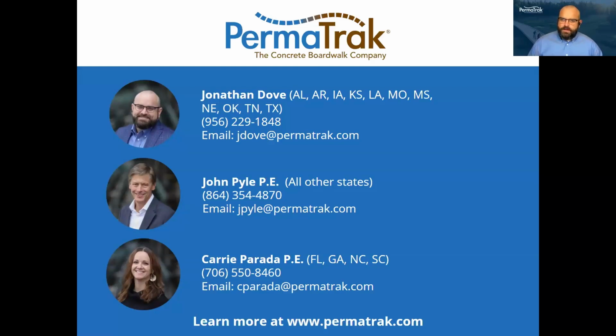That was great. So we had a specific project question where the water was diverted under a boardwalk and washed out some of the foundations, exposing a section of the helical piers that were not protected with concrete. How severe is this issue, and is there a best practice for both repair and preventing the issue from occurring again? So essentially, we've got some scour or erosion related to some water drainage underneath a boardwalk, and it's exposing the helical piers. And so, how big of a deal is that, first of all? And then what do we do to either repair it or prevent it from occurring?